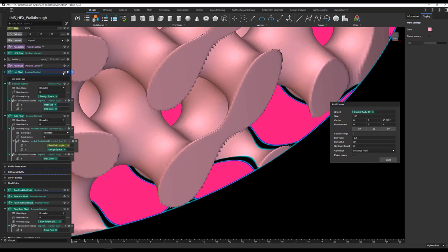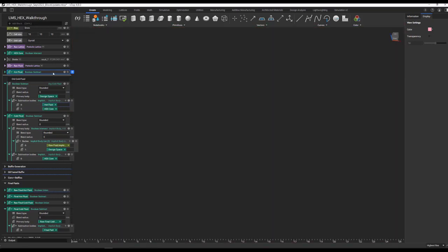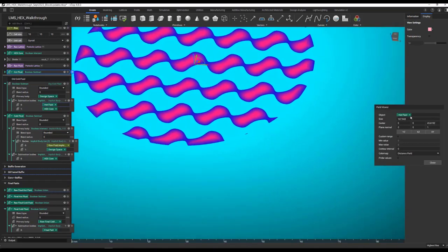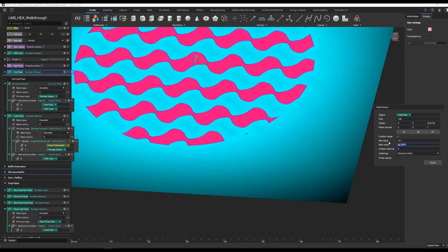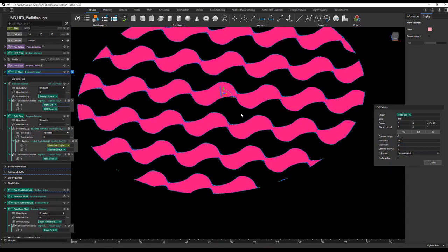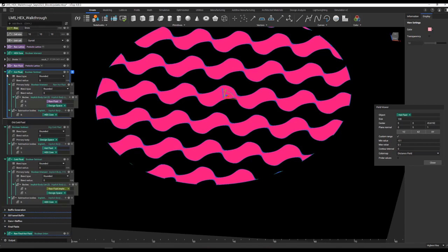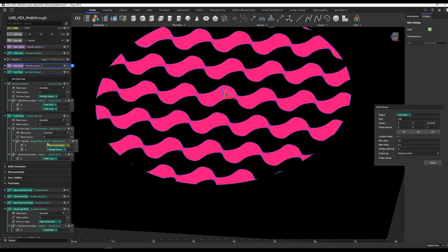I noticed, however, that if I looked at the field of the hot fluid and we set this same range, 100, those artifacts don't persist. So in other words, the fluid domain that stems from this periodic lattice gives us a clean field. A workaround, until we're hopefully able to implement this as a product solution, is to take simply the negative value of the periodic lattice body.